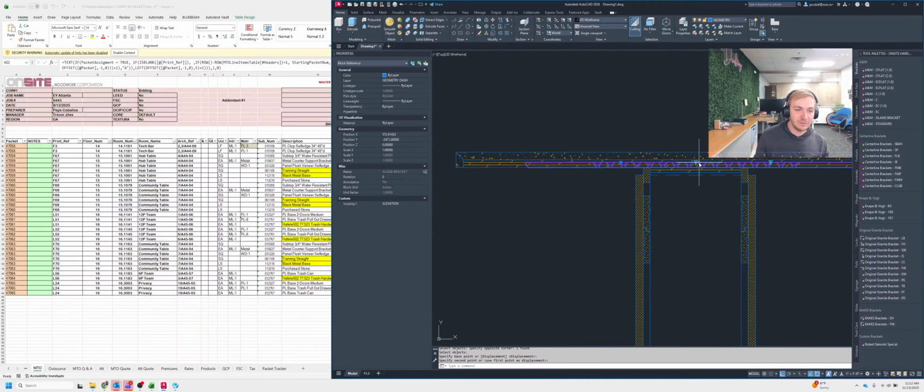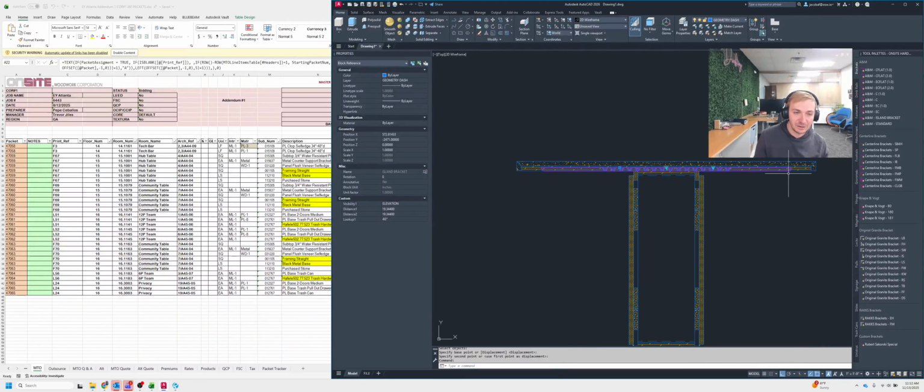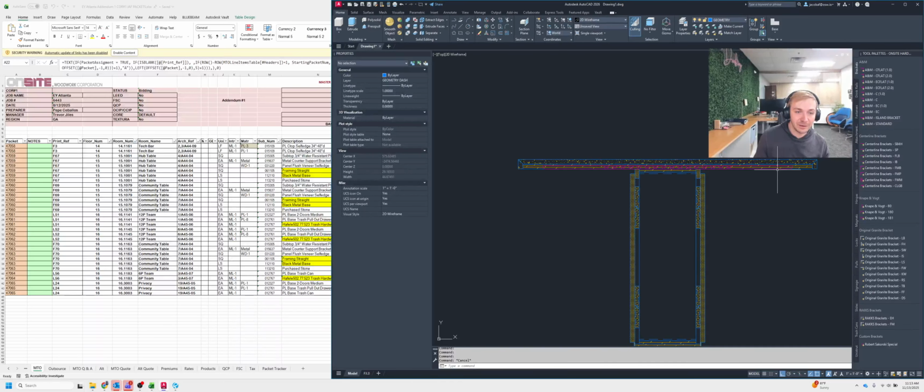So I'm going to check if I go to 40 inches, it does not interfere with the stone and it's not going to get too close to the edge, but it's going to cover way more of this cantilever, or the overhang. You definitely don't want to go 15 because 15 is not going to do anything there. 34 may be okay, but 40 is definitely going to support it well enough. So we're going 40 inches wide for the arm of the bracket.